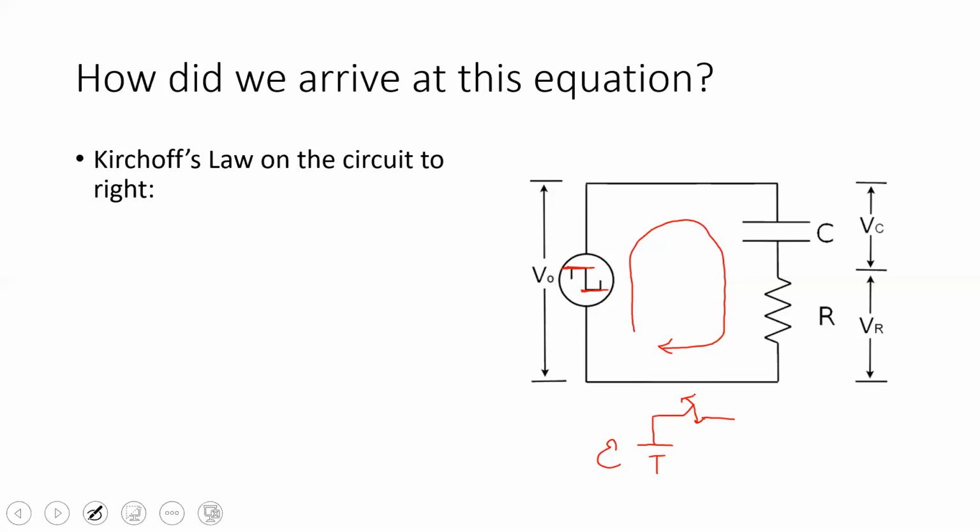So we're going to see what happens to the voltage across our capacitor when we open that switch and our step function generator is supplying 0 voltage. And again, in this experiment, that's kind of an imaginary switch. So I like to draw my loops starting with the thing that's supplying the voltage, and then looking at all the elements of the circuit and saying that they are using up that voltage that is supplied, and when we get back to the starting point, we say it's equal to 0. In your lab, this equation is written instead with some things on the left-hand side and some things on the right-hand side. Both of those say the same thing, right?